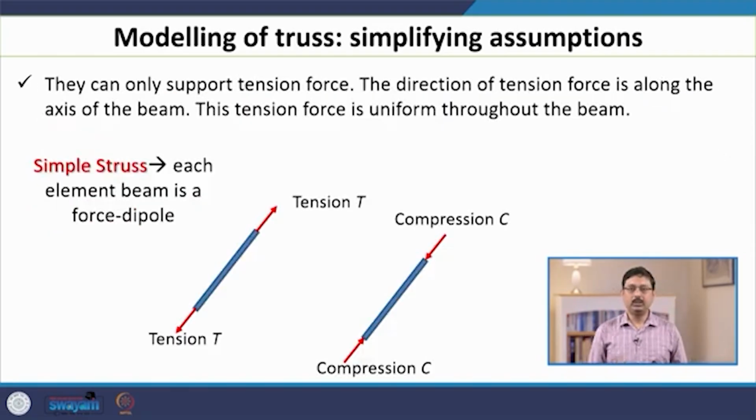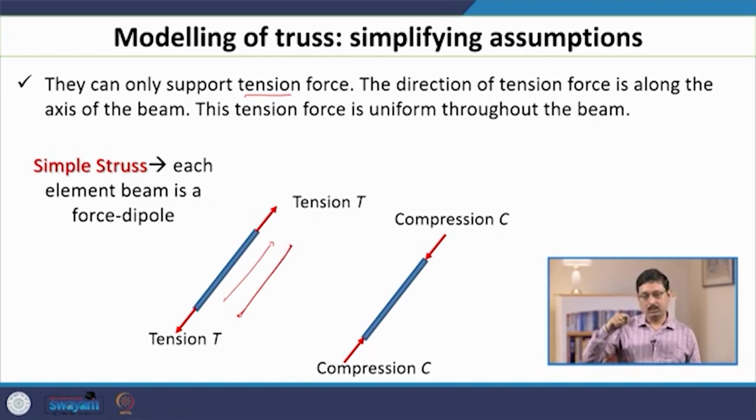If you ignore all those effects, then the only internal force that the beam can support is the tension, which is a force acting along the length of the beam, in a direction tangent to it, and we are going to assume that there is no bending of such beams. These beams are basically straight lines. So, there is no curvature of the beams, unlike the previous problem that we discussed of a suspended cable or hanging rope, where the rope was perfectly flexible.